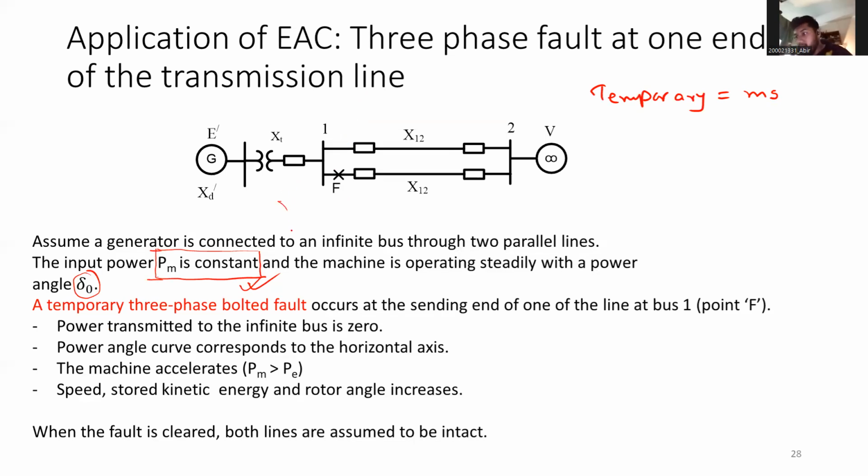What can be the other possible scenarios? You might have a tree over here, and because of a big storm or huge amount of wind, your tree starts swinging. While swinging, say it somehow touches this wire. So it is getting a shorted path to the ground via the tree. Let us assume that the tree is wet.